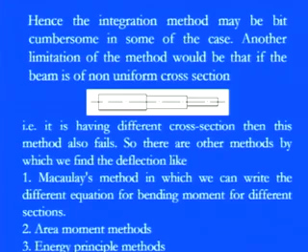So we need to go for alternative methods. There are three methods available in the solid mechanics theory for undergraduate courses, which we can simply apply for this kind of beam, or even for simpler beams. One method is the Macaulay method, in which we can simply write the different equations that come for the bending moment for a different section. Instead of going for the entire beam, we simply take the individual sections, write the equation, apply the boundary conditions, and get those values.